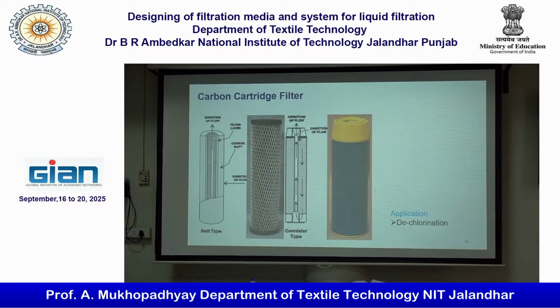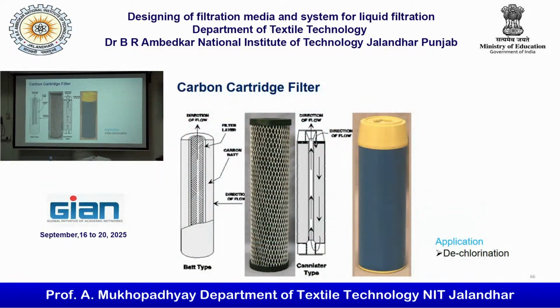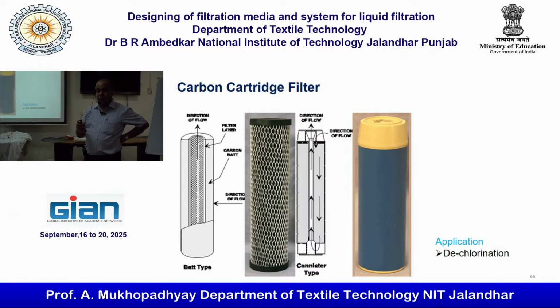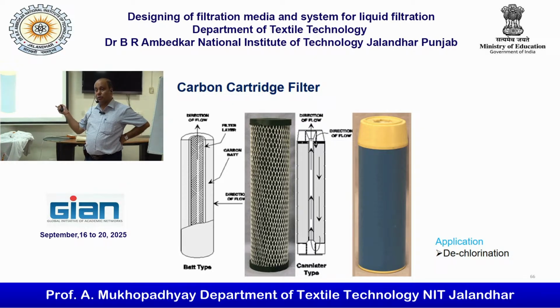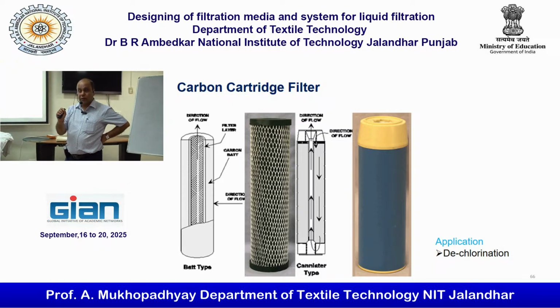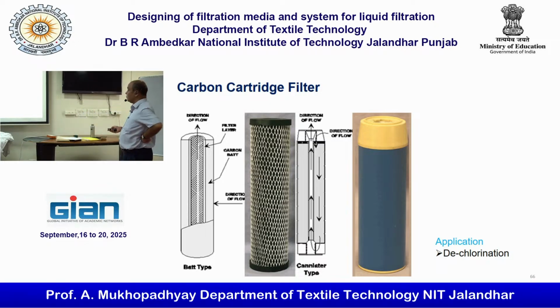Okay. Now this is for better working of the crane. One point I must mention is that whenever we talk about particulates, coarse particles can cause more damage to the crane. It is not the finer particulate matter. Whenever you are breathing, fine particulate matter matters a lot, because it can go deeper into the alveoli. But whenever you talk about the machine or engine oil, then the coarse particle matters a lot. It is the coarse particle that can cause more damage to the material, to the injector engine, in the injector nozzle and also in the hydraulic crane.